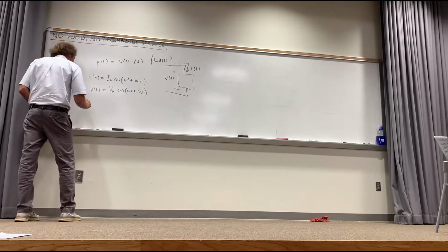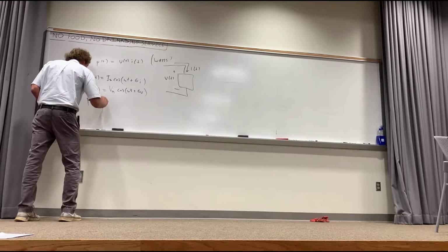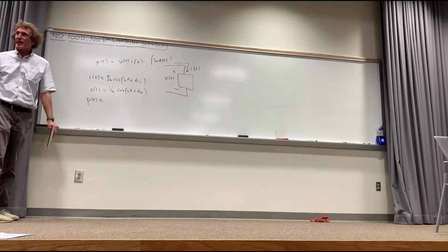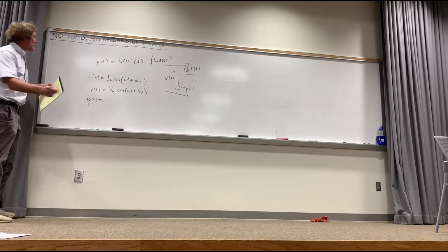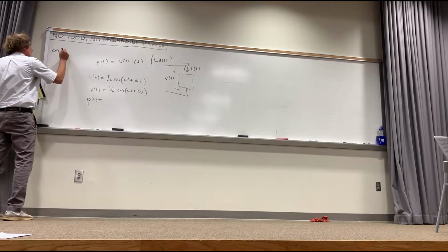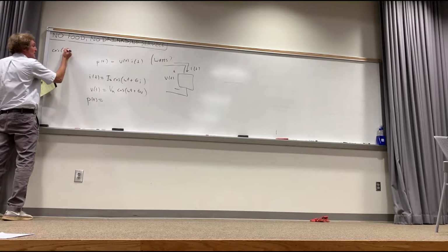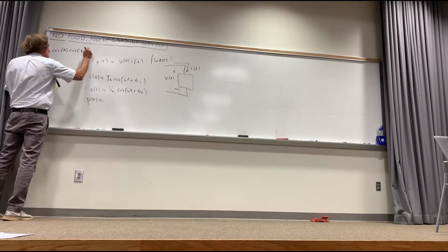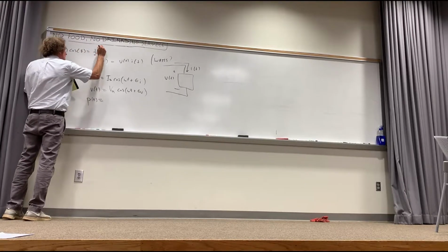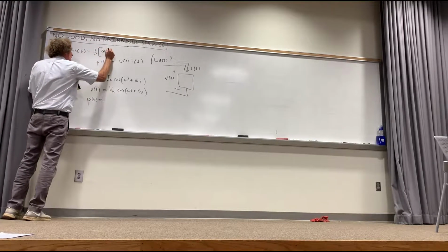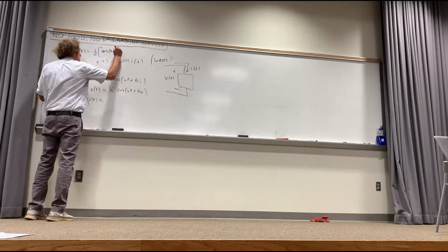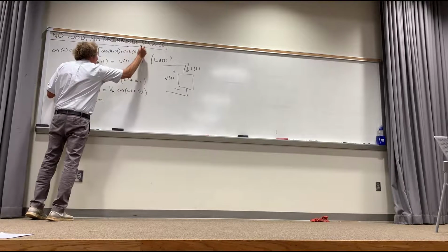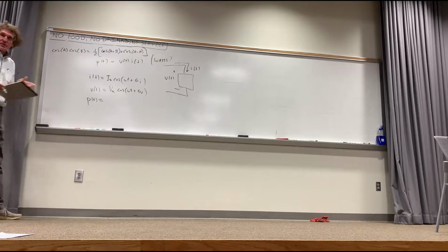Now, the instantaneous power, p(t), since it's equal to v times i, I'm going to use the cosine identity that I did last time. Remember, cosine of A times cosine of B is equal to 1/2 times the quantity cosine of A plus B plus cosine of A minus B. You don't have to memorize that one, just realize that that's the only thing I'm doing here.